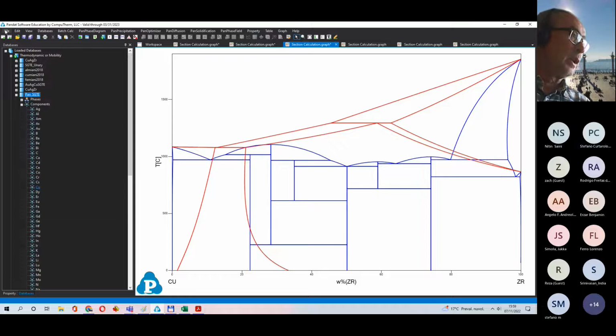It is important because phase stabilization is done by temperature, by pressure stabilization or destabilization, but of course by alloying elements as well. So you can have some phases which are unstable in most conditions, which are stabilized by other elements. We will see its usefulness.